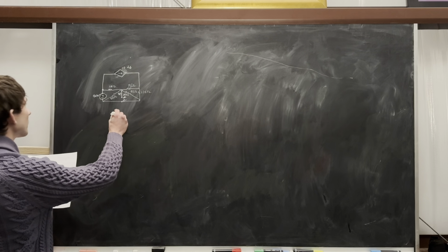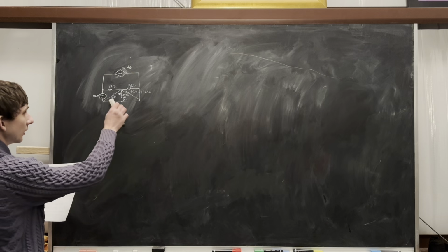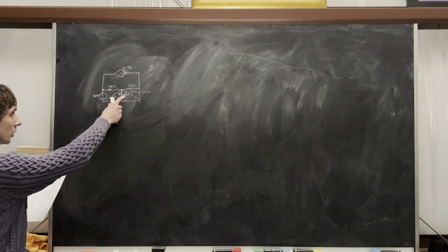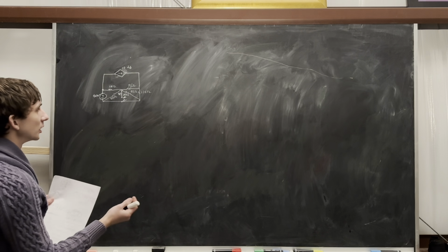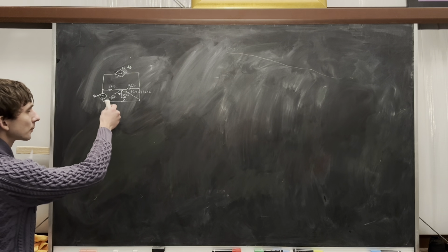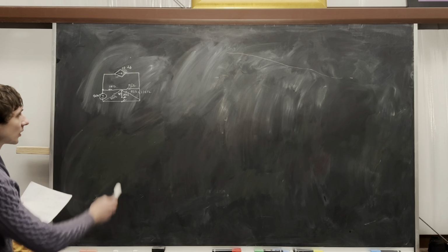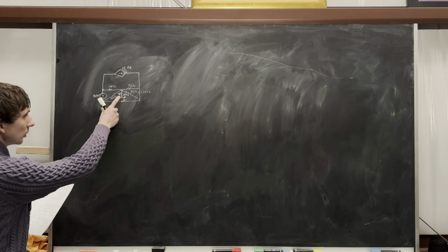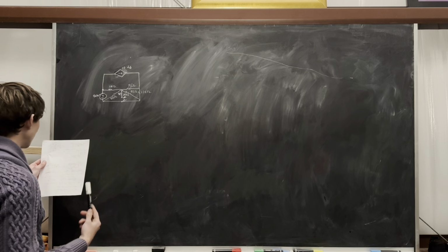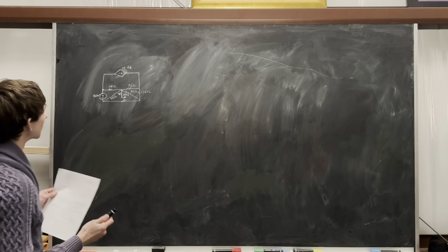This is problem 476 from the back of the book. They don't quite draw it like this. They talk about you wiring an ammeter to measure the current through this 50 ohm resistor here. If you've ever used an ammeter, you know that you open the circuit and then you wire the ammeter in series with whatever component you're trying to measure the current that's going through. So I just put a little open here and put A and B here. I'm not going to go through the whole problem. I'm just going to calculate the Thevenin equivalent, and then I'll leave the rest up to you if you so desire to complete it.